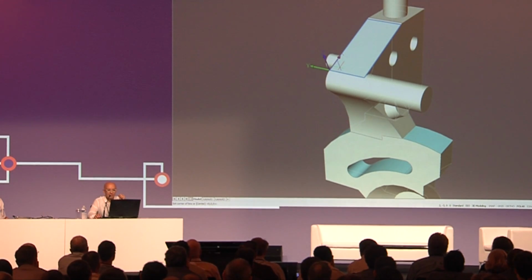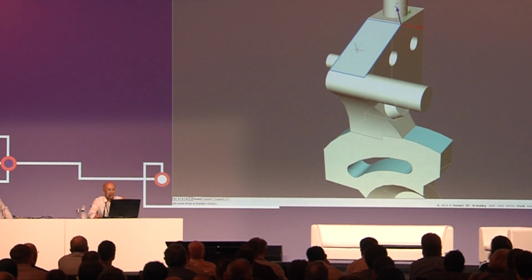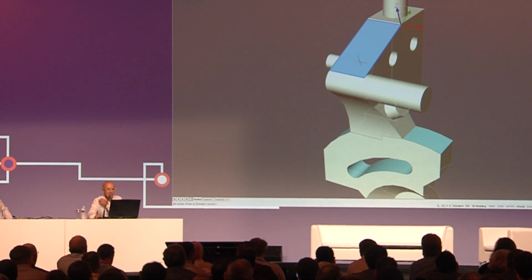And that's important, because in other softwares you can't lock it. And so you can only draw something on top of this face, because else, if you start clicking here, then this is the coordinate system that is going to be applied, and not the one you were hoping for. So here I will now click my Shift key, and you see the color changes, and it's locked. And now I can move outside, and it doesn't change any longer. That's important. It gives you a lot of freedom.